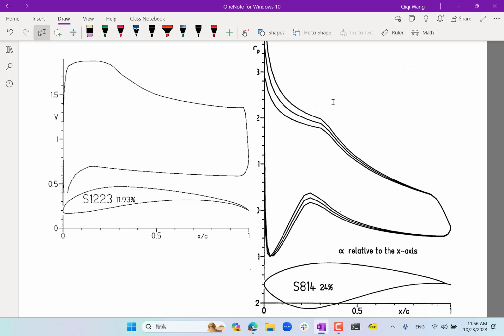Well, for the high Reynolds number case, the flow is going to transition somewhere over here. That is why in the laminar portion, you have the same trend. Initially, when the boundary layer is very thin, you can afford to have a high pressure gradient. And as the boundary layer becomes thicker and thicker, you can afford less and less adverse pressure gradient. That's why you ease the pressure gradient over here.